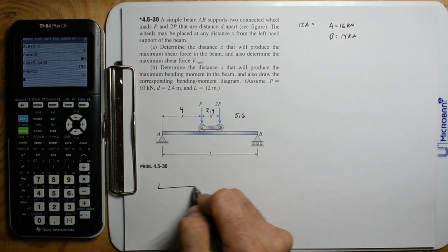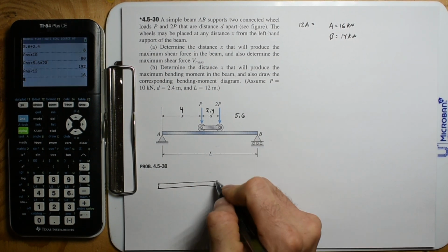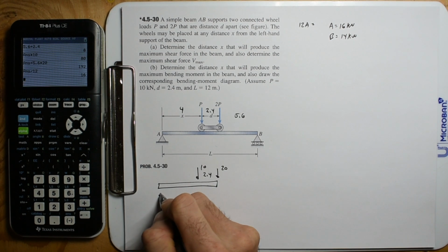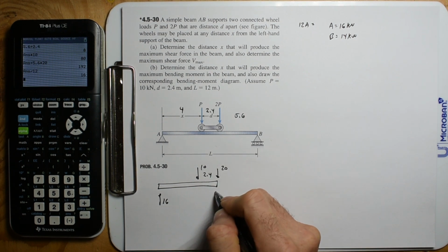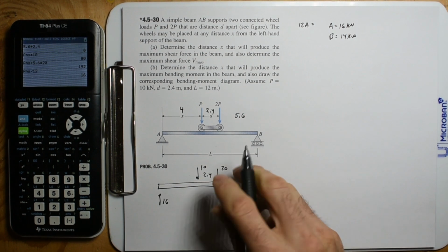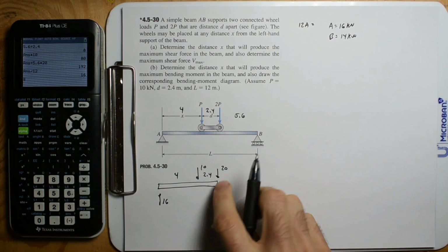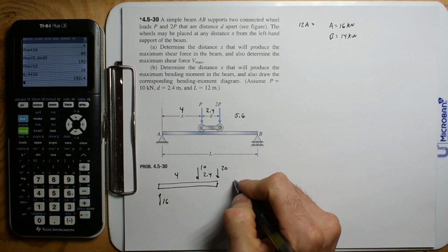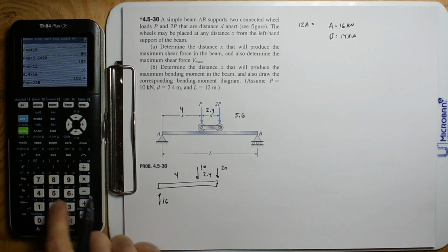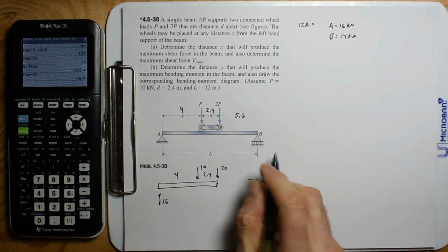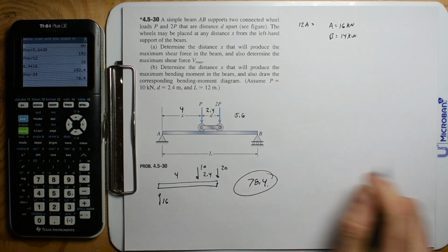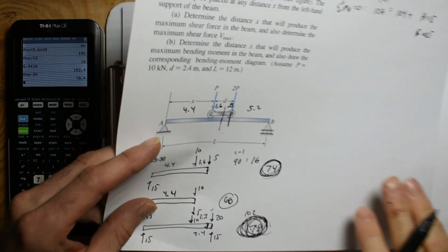All right, let's do our free body diagram all the way up to 2P. We're going to have 10, 20, 16. It doesn't matter what the shear forces are, so let's not even do those, but we're going to have 4, and 6.4. 6.4 times 16 is our negative moment minus 24, and that's going to give us a moment of 78.4. That is part of the question. They want to know the maximum bending moment, 78.4 kilonewton-meters. And that's the biggest number that we got. We got 78 right there.